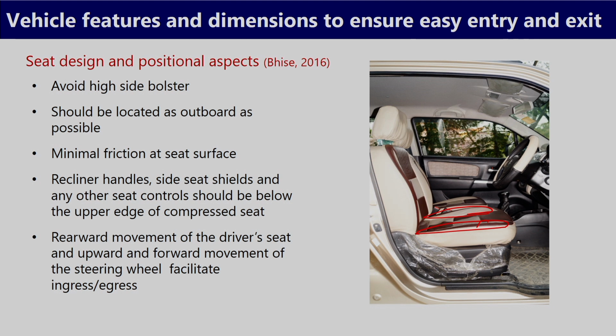Moreover, the seat should be located as far outboard as possible, so that the distance between the outer edge of the rocker panel and the seat is minimum. Then, minimal friction of the seat surface. The material and design of the seat surface should not create any friction which resists the easy movement of the driver or any other passenger from the seat.